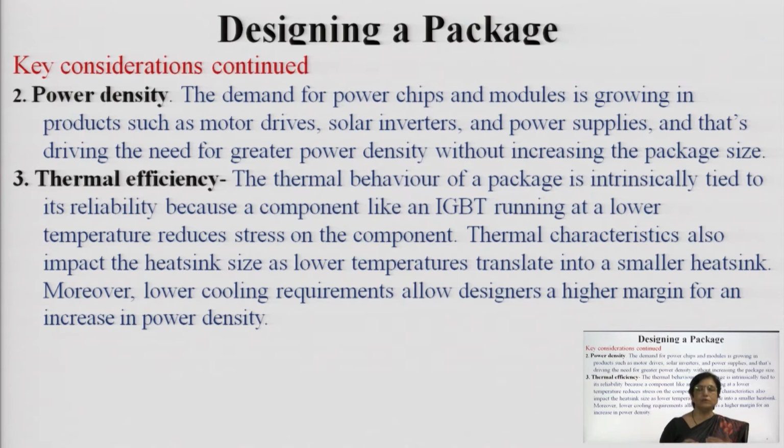The package also needs thermal efficiency, because the thermal behavior of the package is intrinsically tied to its reliability. For a component like an IGBT, that is an insulated gate bipolar transistor, running at a low temperature reduces the stress on the component.